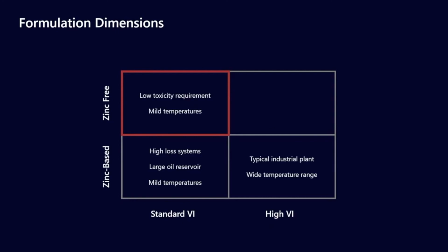So maybe you work over a water source, right, and you need that zinc-free requirement. And finally, zinc-free and high viscosity index, that's when you might need something with a low toxicity, but it's not essential, where you're going to be either in ambient temperatures that have a very wide range, or operating temperatures that have a wide range or at the top end of the range. You have a need to keep it clean, or you have mobile equipment, which sort of encompasses all of that.